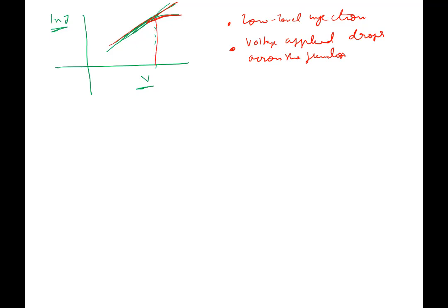Note that once the diode is no longer exponential, the characteristic is actually going towards linear. It's tending towards ohmic behavior, tending to a linearity. Okay. Now that's not very good. Because remember, you're using diodes in various applications and you want the diode drop to be very small. You don't want a significant drop across the diode here.